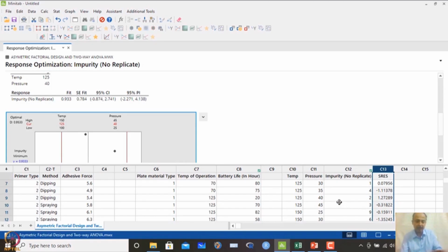Now we are entering into design of experiments, but before that, we need to know one important topic which is known as measurement system analysis. We will discuss measurement system analysis and why it is so important, because before I go into design of experiments, this is one area we should understand. If the instrument is not correct, then the measurements that we are taking have no value. Until we measure accurately, that has to be ensured.